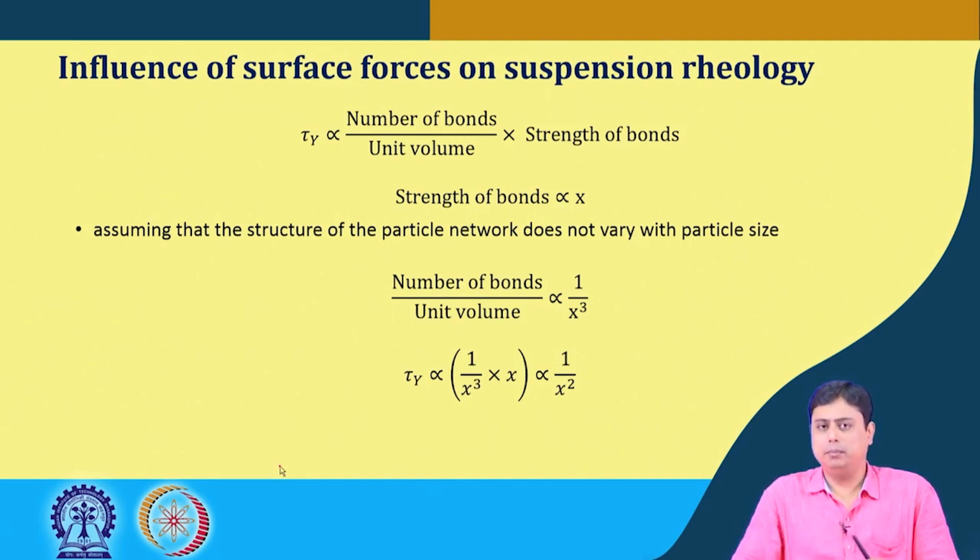So this is another big difference between these two approaches, because here we have seen that the particle size influences the surface forces, and once we take into account the surface force, the particle size will consequently influence the suspension rheology. But in hard sphere there were non-interacting particles, so the size was not of any consideration in that approach.